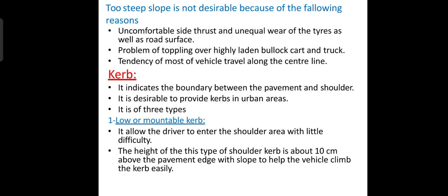Too steep a slope is not desirable because of the following reasons. Uncomfortable side stress and unequal wear of tires as well as the road surface. Problem of toppling over of highly laden bullock carts or trucks. Tendency of most vehicles to travel along the central line.